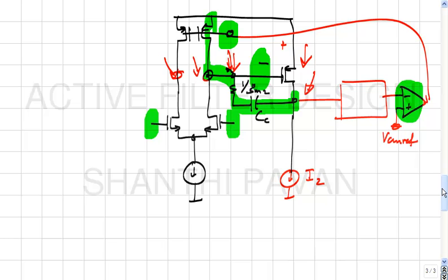So this is a problem with using op amps, using one CMFB loop for both stages, right. So you can get stuck in this all 0 state, in which case it does not matter even if you design the world's best filter, it just does not start, right. It's like having a BMW but without the spark plug, it does not help you, you understand. Yes sir. Eventually the overall input will propagate, and that's what you are hoping, right.